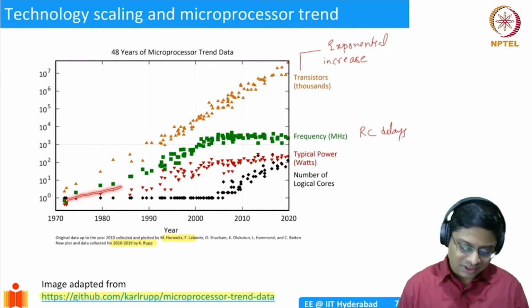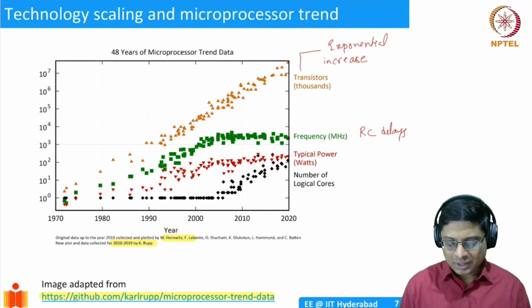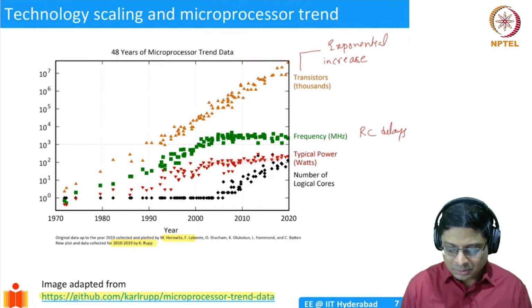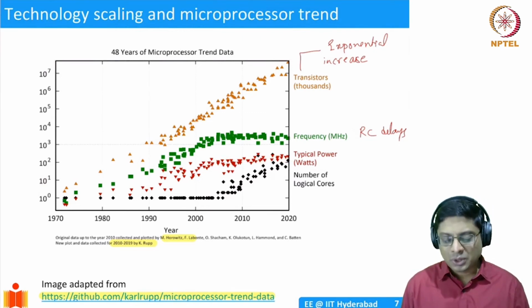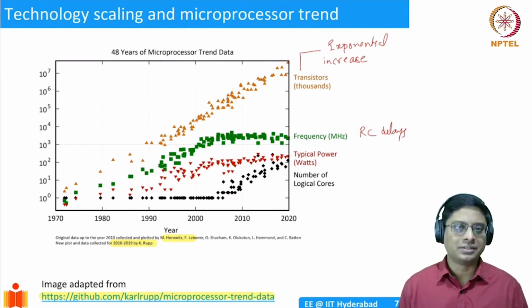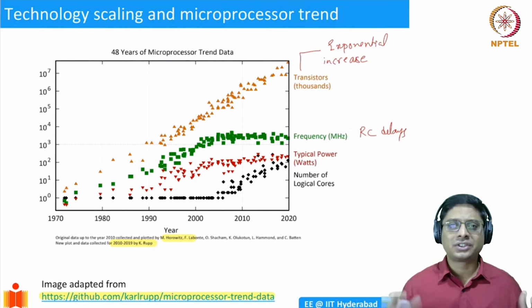You see that initially power was increasing because we are increasing the number of transistors. But then after some time, we are not able to increase the capacity more. The reason is if you have more power dissipation, you're heating up your silicon. Once you heat up silicon, we know all bad things will happen. Mobility can reduce, and threshold voltages can shift. Whatever transistors or circuits you have designed so carefully might not work as you want them. So we don't like them to be heated.